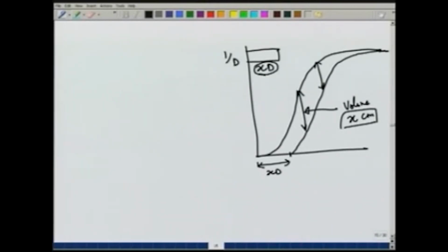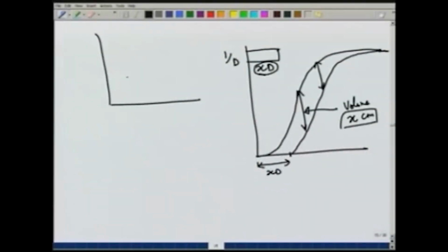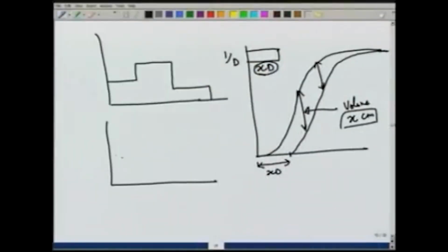Now, this works well when we have a rainfall hydrograph which can be idealized as rainfalls of constant intensity over certain duration. We have also seen that for derivation of the UH, we need rainfalls of similar kind, where we have a constant intensity d hour